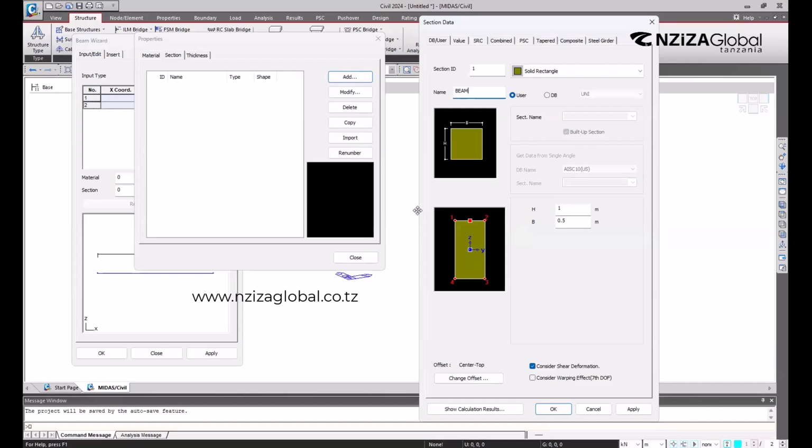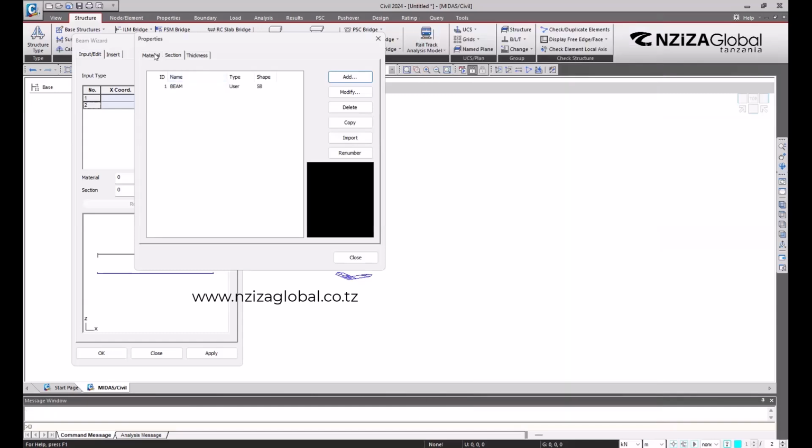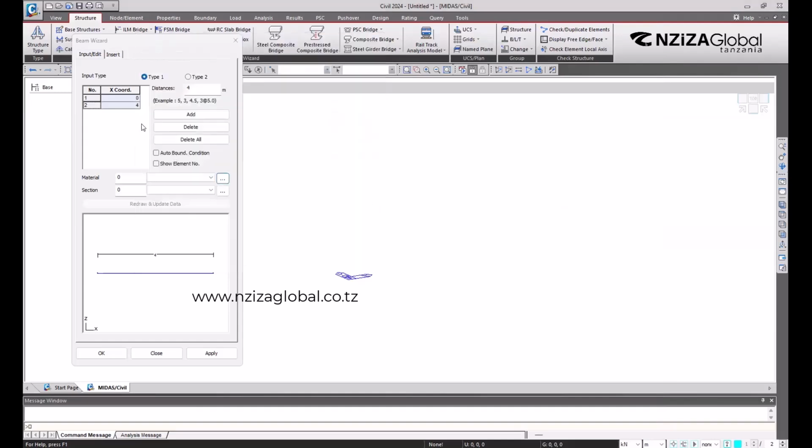We can change. Let's run this. The top is the axis position. Yes, let's run. We will see all those models. I want you to understand this. So don't worry. Let's click OK. Now you have our section and you have a material, right? Then I close. When I come back here, you see I can choose my material class. Also, I can choose my section. On the thickness, just the way we define it now, it's not necessary.